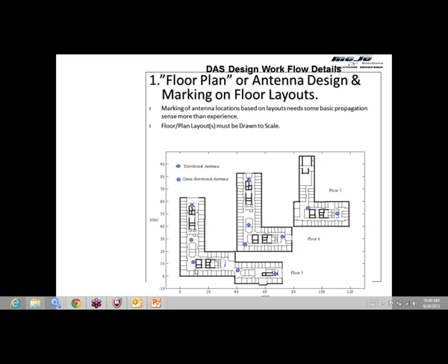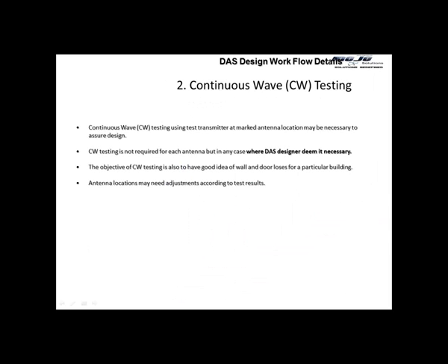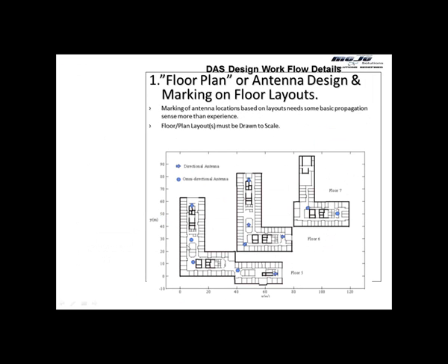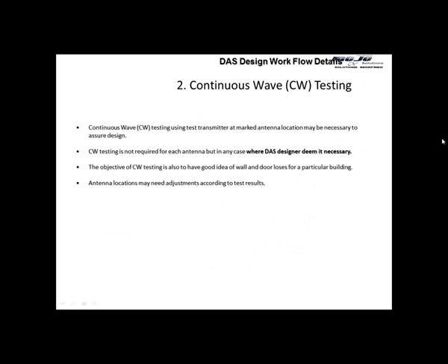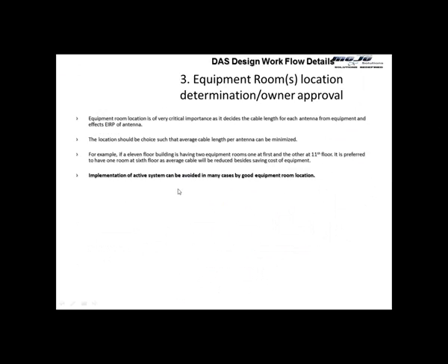So looking at this, you understand that there is a thought process when you start to mark antennas on the paper or put antennas in iBwave. You drag and drop the antennas in iBwave. There is a thought process behind it. Okay, so it's done according to that, which I tried to explain. So once you are dropping down the antenna, you may come and see, okay, what if I install an antenna over here? What will my signal be inside this place? You can come and question this.